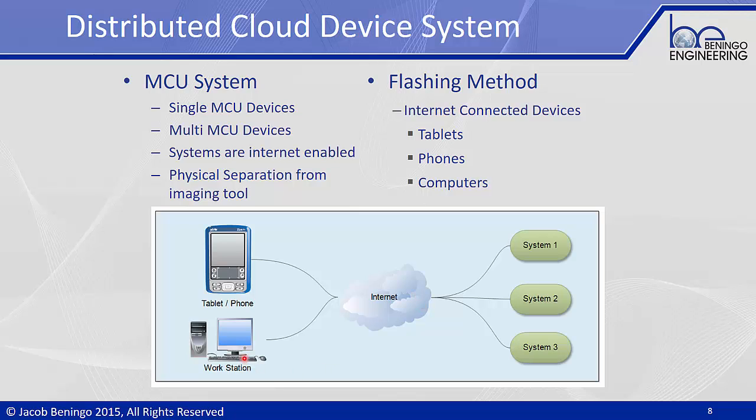And what we're doing then, perhaps we could be using a workstation or a tablet, but more likely we're using some type of server-based system which has the ability to push updates out to the individual devices, perhaps in batches. The idea is that we're then able to have the embedded system directly connect through the internet to some type of server or update tool that is then going to architect and guide the firmware update process. So it could be that we're going from the server side, pushing firmware updates down, or it could be the individual systems are periodically going up and saying, hey, do you have any new firmware for me? And then they're updating themselves.